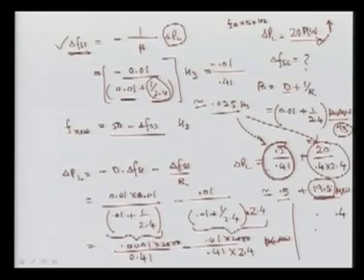For example, suppose your change in frequency is 0 and the load is increased; the change in loading means your frequency at steady state is going to be this value, so there is some reduction in the change in frequency, meaning a fall. On the other side, if it is a release, then the frequency will go to some steady value here.